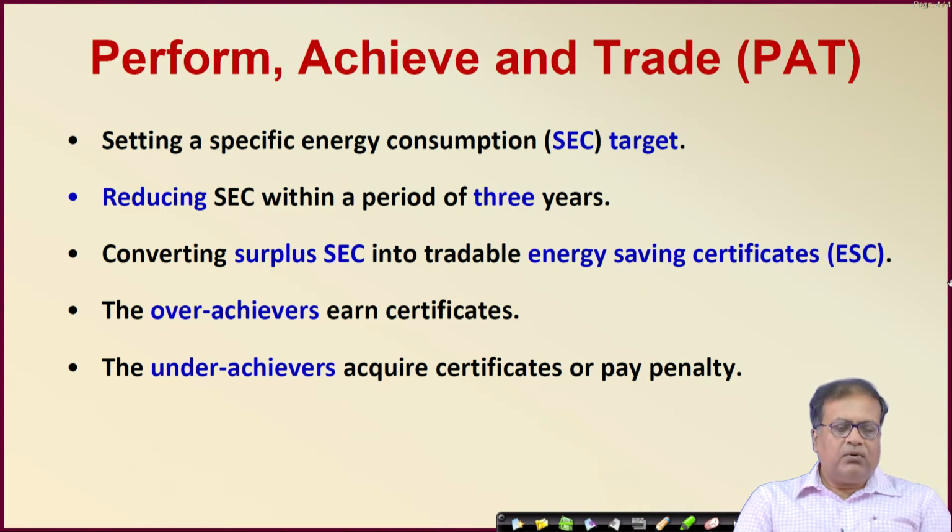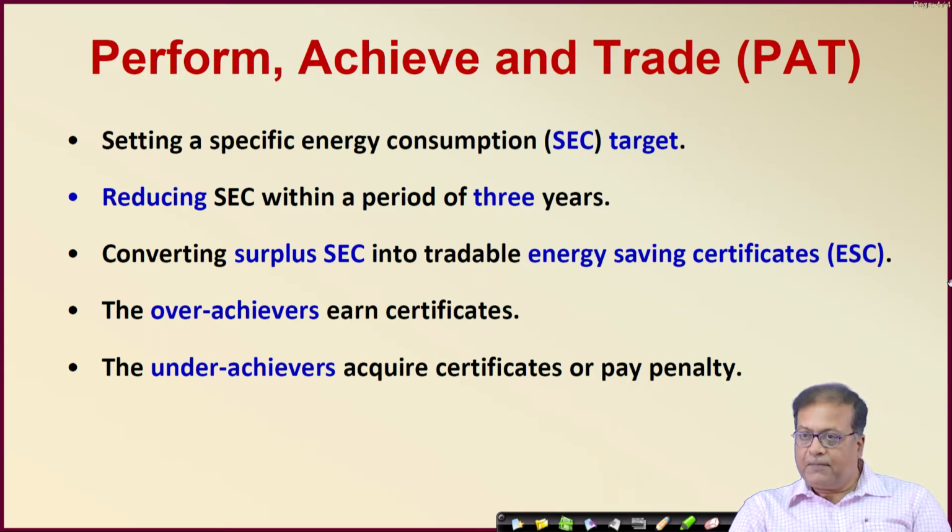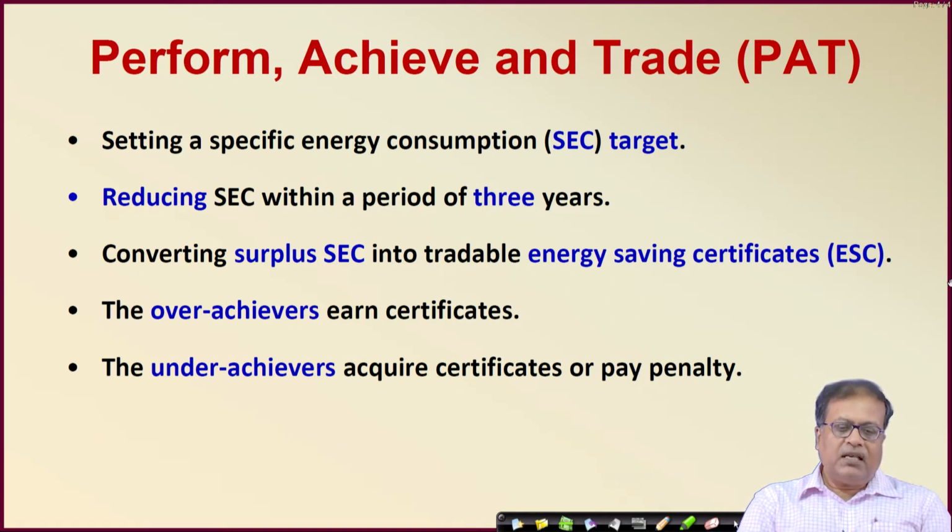So, already I told you, but here is, in a nutshell, what is this PAT or perform, achieve and trade. Setting a specific energy consumption target. So, specific energy consumption, SEC, is one of the major issues, reducing SEC within a period of 3 years.